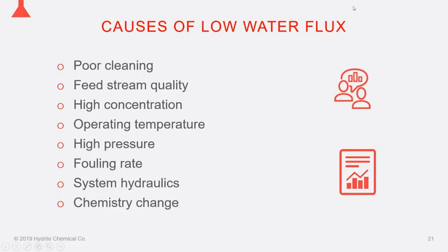So we need to check for chemical concentrations. Do they get the right pHs during the wash? Is the surfactant pump working? There's no greater way to mess up a membrane system than if they don't get the proper amounts of surfactants during the washes. Since we're not titrating or checking pH that tells us surfactant levels, sometimes what can happen, as I've seen, is a surfactant pump can fail, and we don't get the right amount of surfactant, or we don't get any at all. And the system can actually run a day or two without that before it totally crashes. So keep that in mind.